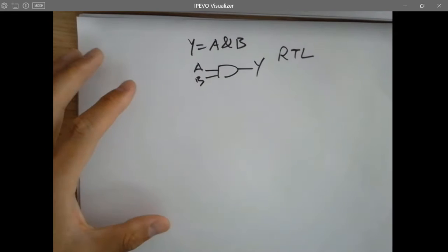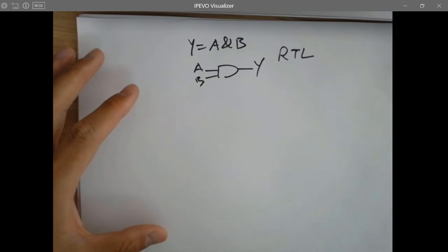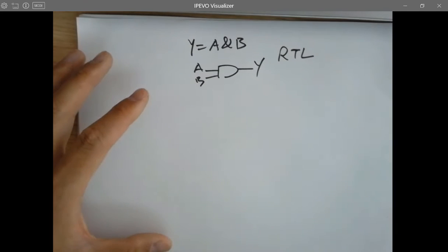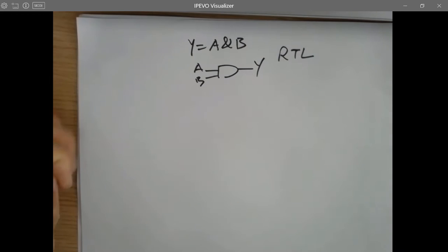But after you fabricate it into chips, you just look at the chip, the die, under the microscope. You can see the structures. You can probably duplicate it a lot of times. They will look at the metal layer, even though they don't know what's going on, and just try to duplicate all the connections, since you can see every single connection. So on the top metal, you see the connection, duplicate it, draw that schematic, and then etch it.